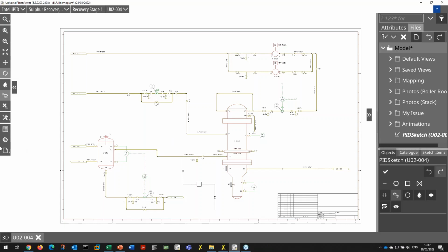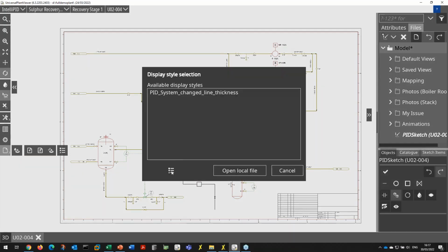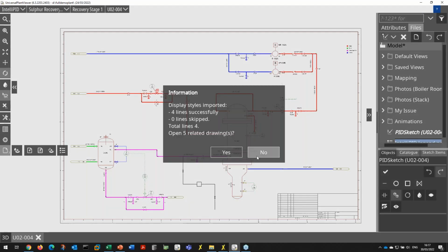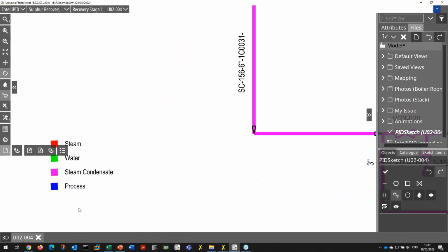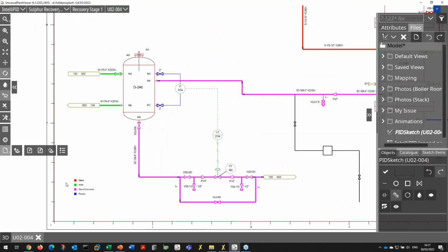As a next point, I would like to show you colored legends. For that, I load a display style which colors my pipelines, and I activate my option for placing a legend along with this display style. Okay, when I open up this, you see the default location of my legend is over there, and also my, let's say, default font size is predefined.